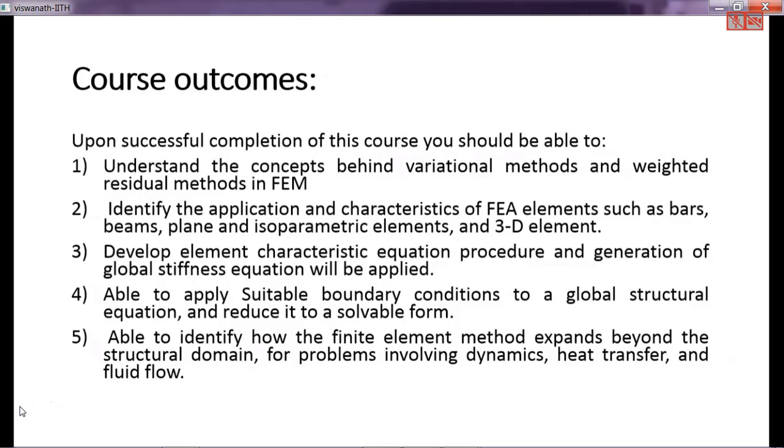In the weak form, you put in the numerical approximation and convert it into a set of linear algebraic equations which replicates the same equilibrium equation that is there in the analytical form. Once it is a system of linear equations, you can invert it and find the solution much more easily compared to the PDE form. And once you know the solution at the assigned nodes, you can even obtain the solution everywhere inside the domain using the interpolation function.